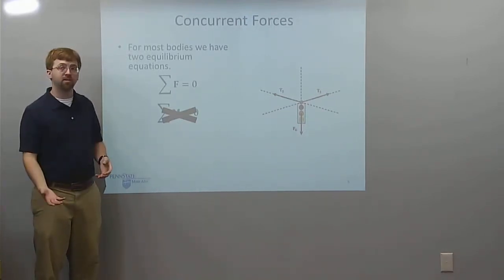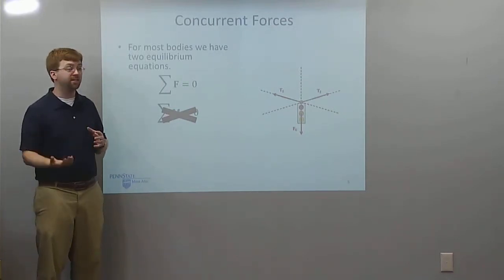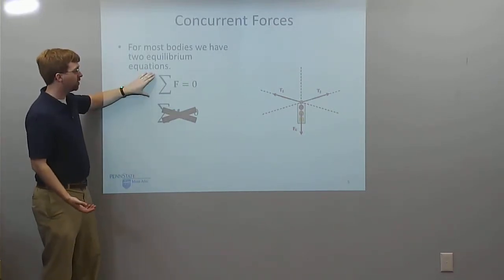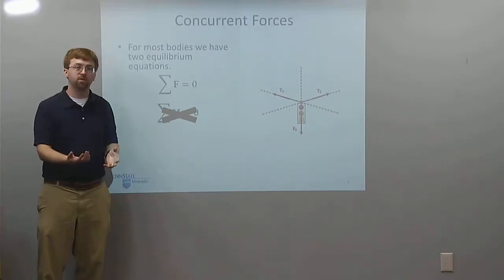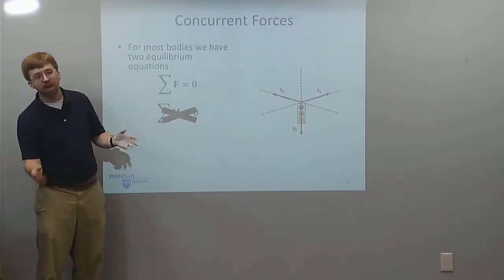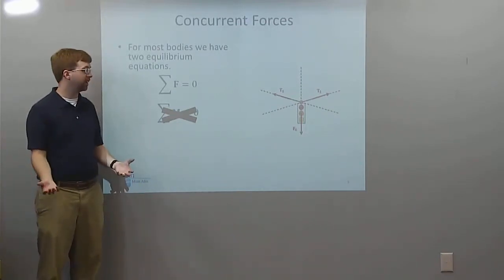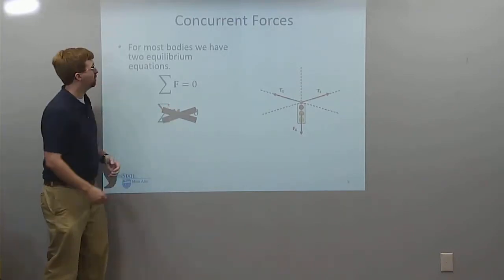So with concurrent force systems, it actually gets a little bit easier, because usually we can just concentrate on the sum of the forces equation. So we can do sum of forces in the x, sum of forces in the y, sum of the forces in the z. We don't have to worry about the moments.